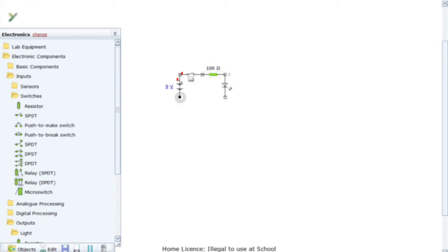So as you can see here, just completing this little circuit with a wee switch involved, and you might get this situation where you try and switch something on, whoops, doesn't quite work, does it? Now obviously the resistor isn't high enough, it's not protecting the LED at the output, so you might need to change the resistance up a bit. You can do that by going into it, and again you can test it, and you might get several of these. It might be a situation where something just doesn't quite work, and eventually you'll get it working and the LED will go on. So that's one of the outputs.